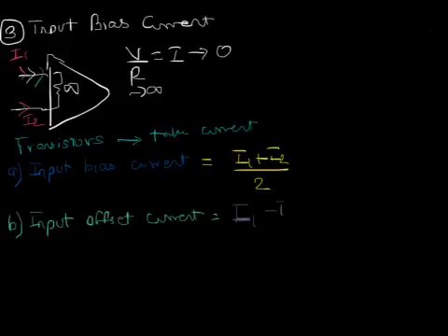What this means is that the current going to the op amp is kind of tilted, and so one side is giving, say, a higher current than the other, and you want to measure how different the two currents are, and that is what the input offset current gives you an idea about, while the input bias current gives you an idea about how much current whatever is connected to your op amp, that source, is going to have to pump into the op amp.